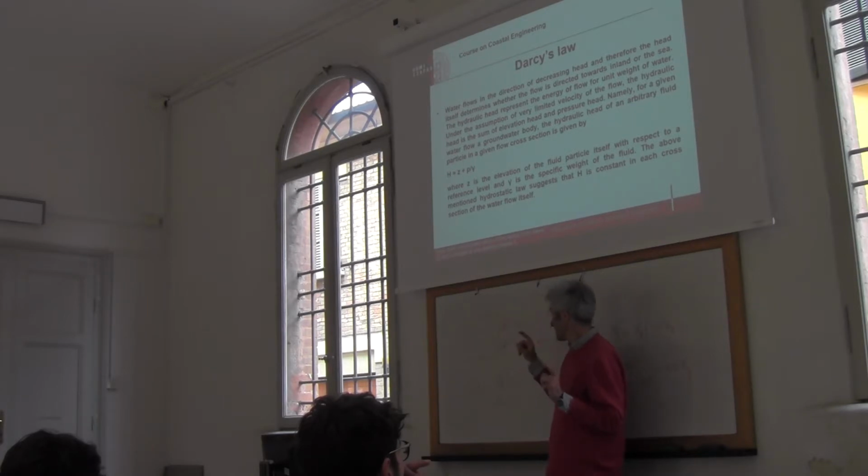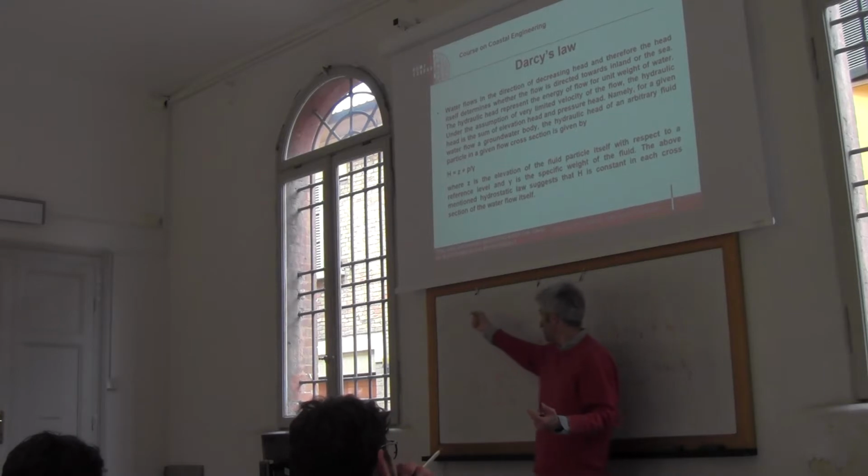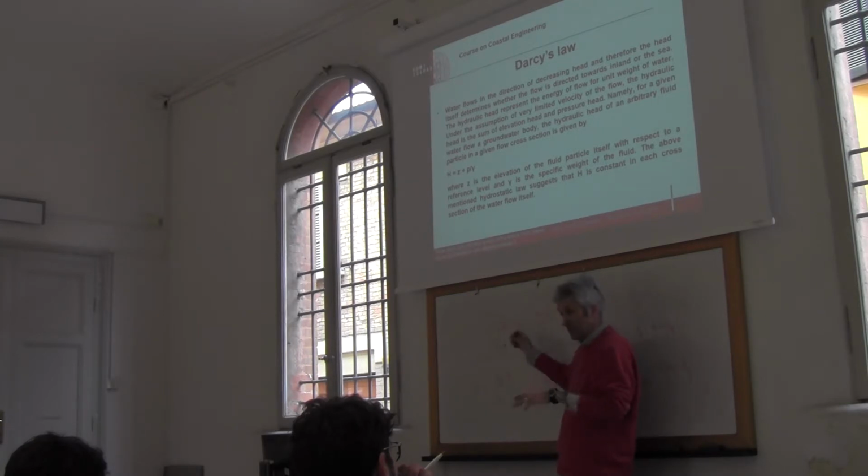It means that if you decrease the level of the water table because you pump, or because you reduce infiltration through urbanization or whatever, you have a rise of the interface. You push back the interface if you raise the level of fresh water. Another thing that this relationship tells us is that if you don't have any over-elevation of fresh water with respect to the sea level, you have the sea entering completely into the land.